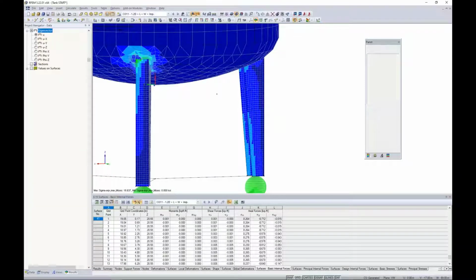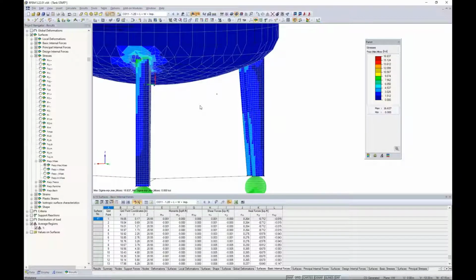So I went ahead and ran this. We're viewing our stresses on the structure just like what we've seen before. And in reality, I'm looking at my von Mises stresses. There really isn't much difference here with my leg on the right-hand side. But I also didn't really scale that imperfection up too high, only 0.014. So I think it can be concluded that it really doesn't have much impact on the stresses at this location, which isn't necessarily a bad thing.